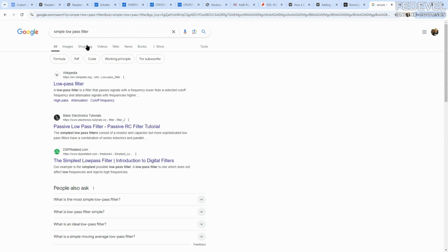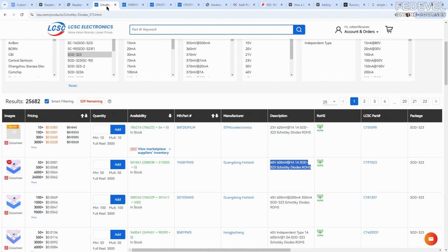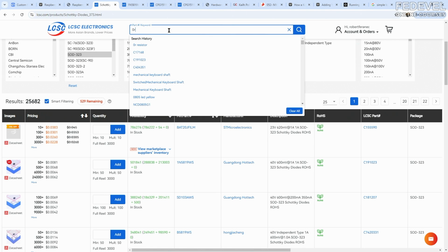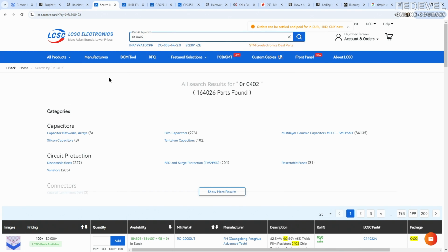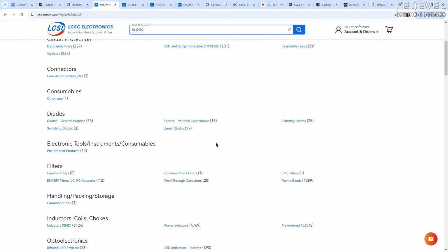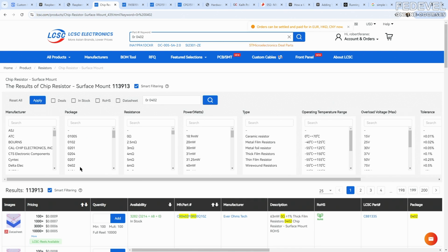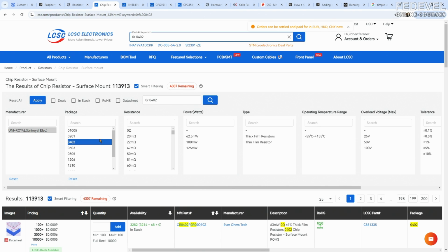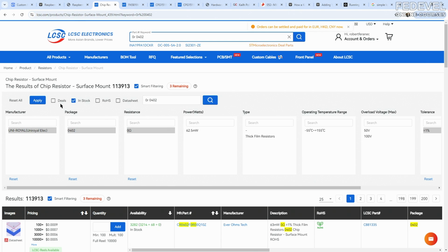And we would like to add this simple low-pass filter. It's just a resistor and capacitor, but we are not going to use it. We will use a 0 ohm resistor initially. And you can use this filter only if you need it. Again, if you have a very large keyboard, maybe the signal may be very noisy, so then you can fit this filter. But on our very small keyboard, we are not going to use it. I just would like to include it in the schematic. It's good to have it there in case you have problems. You can play with this filter.